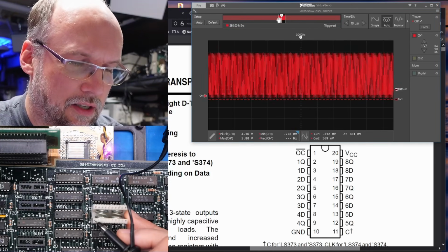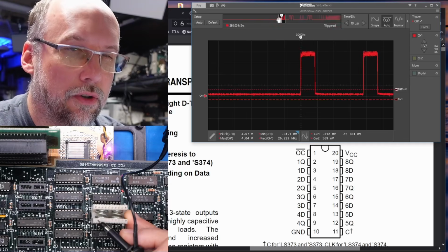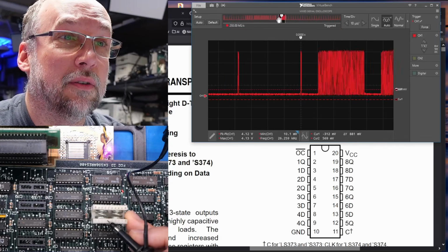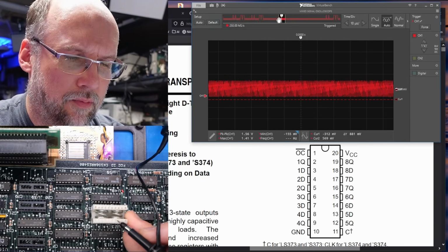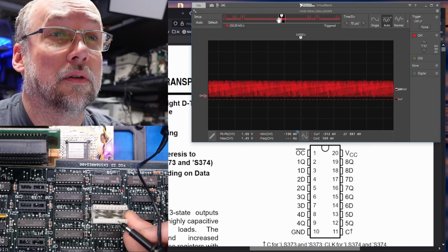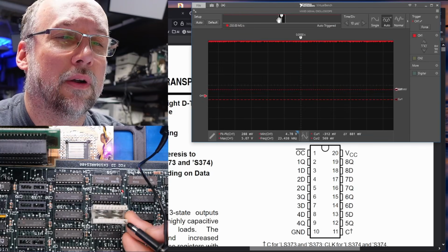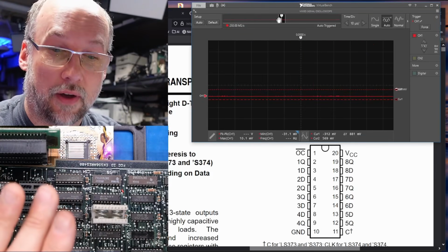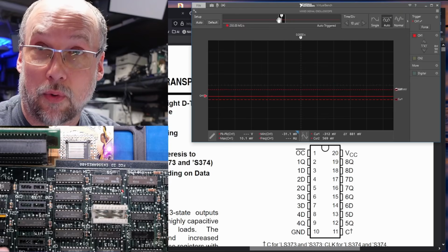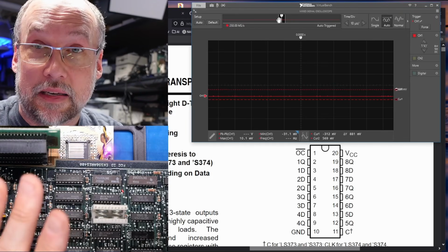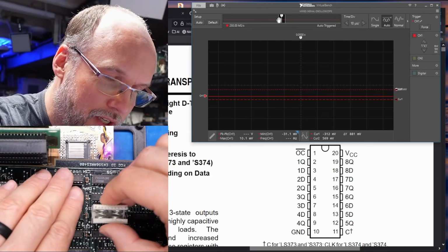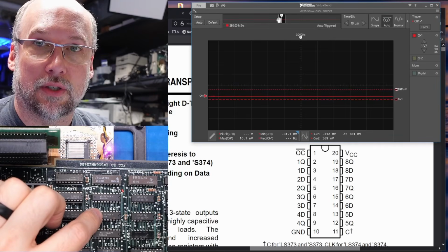That is a clock signal. That is an output 5Q. That is an input, input, output, output, input, input, output. I assume looks fine. There's just not a whole lot of activity on this one, but yep, guess that's okay. And then we're at 5 volts. Okay, so that chip, everything looks fine. What I would expect to see is that when we had a problem, we wouldn't be seeing an output on one of those particular units. So that one there looks totally fine.